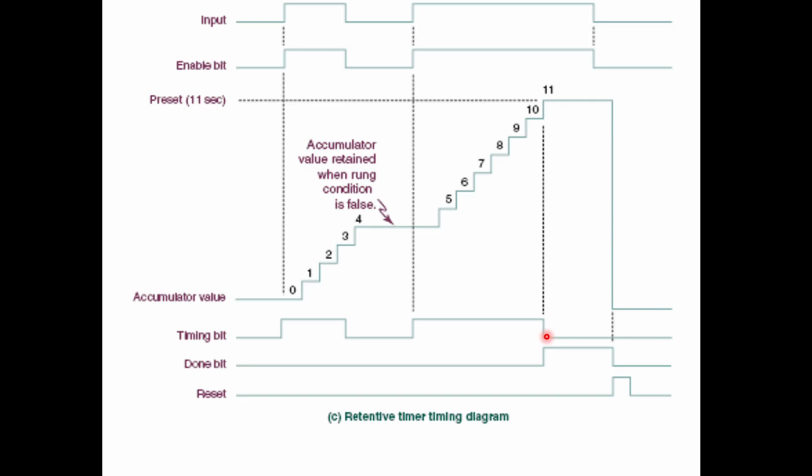So we make sure that the operator cannot access the machine while it is running. As soon as the machine starts to run, we close the safety door of that machine. It is electromagnetic locking or electropneumatic closing, some sort of auto closing system. The door is closed.